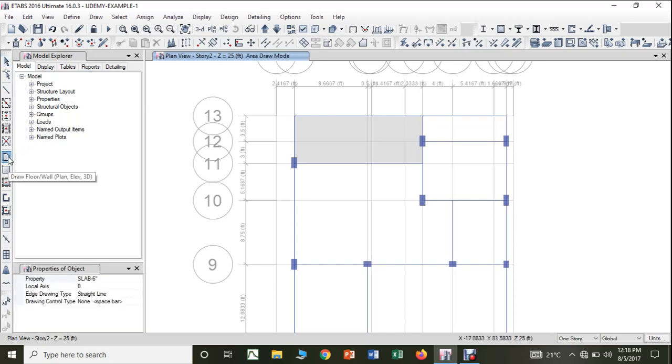Then after that, make sure here that this is a cantilever portion. The cantilever portion slab will not be casted separately. It will be casted along with the previous slab. Therefore this entire thing we will cast once. Therefore I will start from here, here, here, here and here. So this is my second slab that I have casted, right?